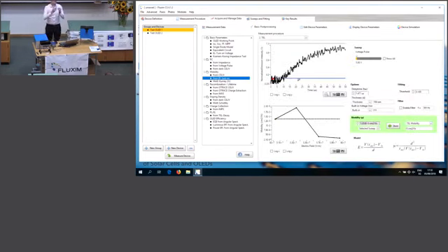So we say when we start the voltage, the light doesn't come out immediately. There's a certain delay time when the light starts. And what we now do is we take this delay time, and we have a certain device thickness, and from that we can calculate the mobility, because it takes a certain time until two charge carriers have reached each other in the middle of the device or somewhere and start recombining. Of course, it's a very simplified image here because we just take an average.